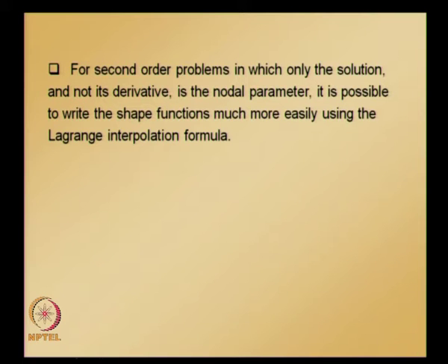The procedure which you have seen earlier, that is starting with a suitable polynomial, becomes more cumbersome when you go for deriving for higher order elements. So the other alternative is to use Lagrange interpolation formula. One point that you need to keep in mind is Lagrange interpolation formula can only be used when the solution, not its derivative, is the nodal parameter.